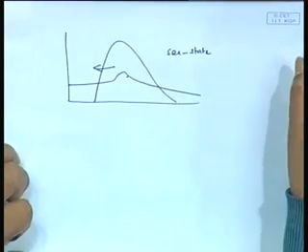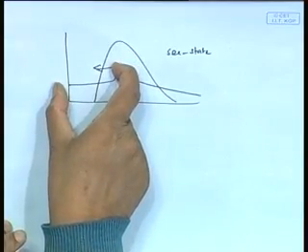Small boats would simply ride the wave. See, suppose you take a small craft, a 30-meter long ship, and it is going in sea state 6 where large waves are 200 meter and above. 200 is about 6 times more length, it will simply ride the wave. But if there is a smaller wave, 50-meter long wave maximum, sea state 2, something like that, it will behave very badly. But take a large ship, a big tanker, 300-meter long, it is not going to even feel those 50-meter long waves, but it will become much worse if I have sea state 4, because then I have mostly 300-meter long waves where it is behaving badly.